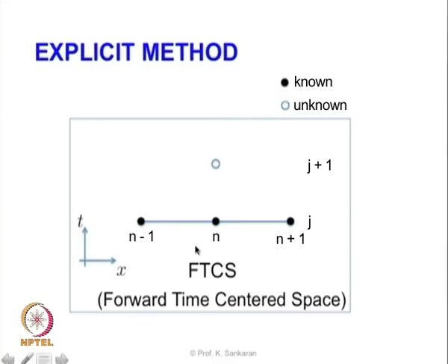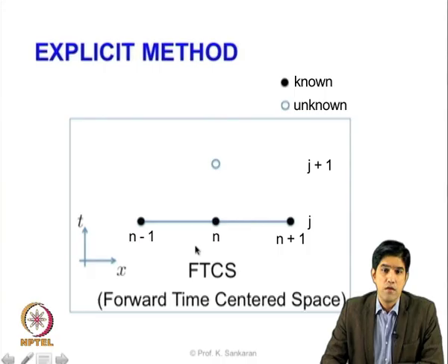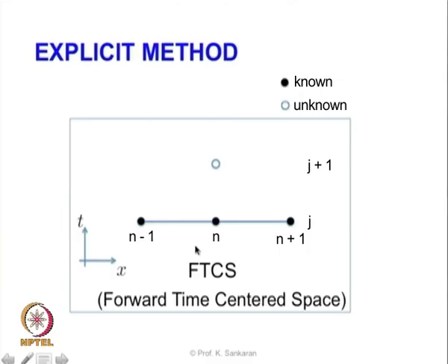Like in the case of the advection equation, this particular equation is very difficult to model for any real time problem, particularly for the reason which we mentioned before, that the delta t is going to be very small. So we have to go very slow in time stepping in order to make the scheme stable, but this is not interesting because you have to wait for such a long time before anything useful happens.